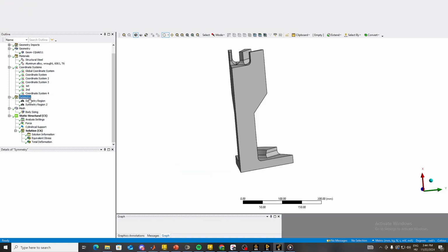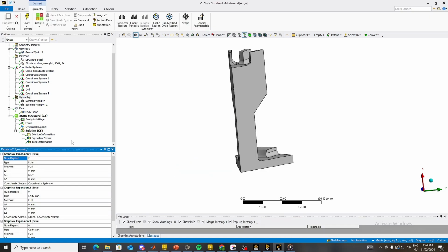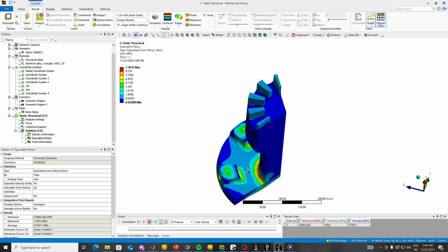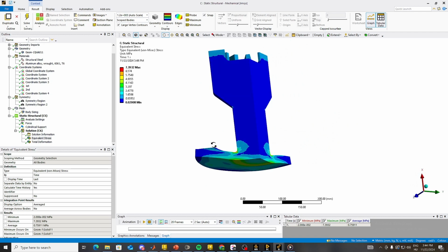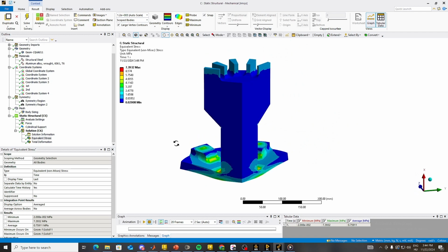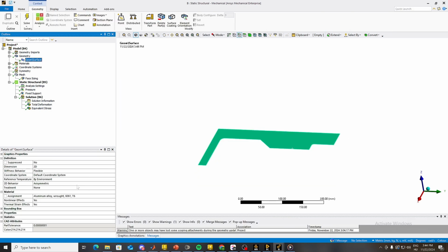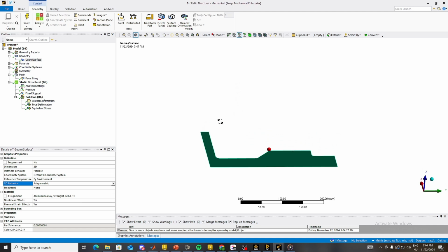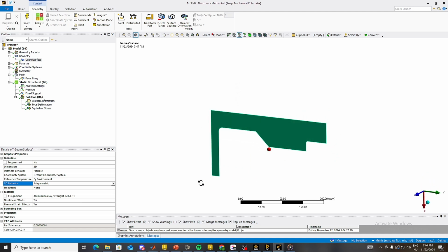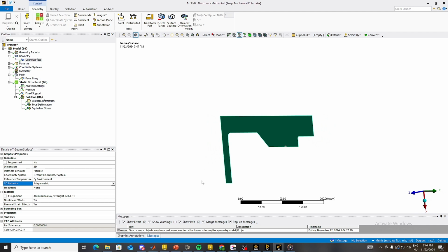We can, for example, even choose to use only 2 num repeats, but basically that is all that is important. So in today's episode we learned how to make a periodic analysis and a 2D axisymmetric analysis. From the 2D analysis there are some other analyses. For example, we can make plane stress and plane strain, but they are usually much easier. Plane stress is usually used when the third dimension does not really matter.